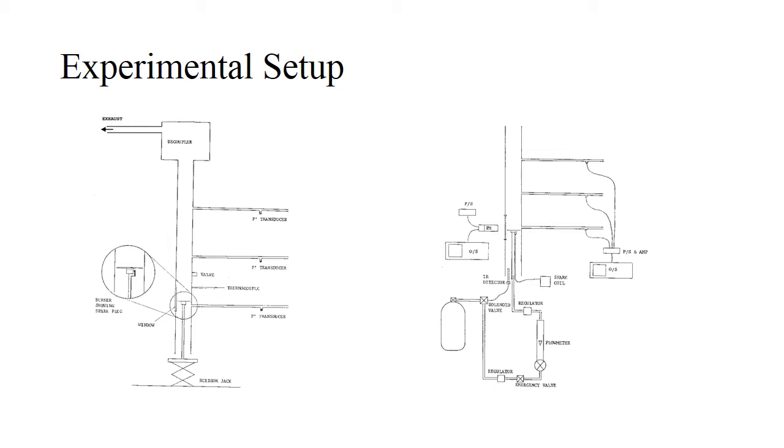On the right is a more detailed schematic of how the devices are connected to the Rijke tube and the electronic equipment that will record the data. The photomultiplier is visible on the left of the Rijke tube. It is positioned before an interference filter that allows light only of our desired wavelength band of around 305 to 315 nanometers, which is the range in which hydroxide chemiluminescence occurs.